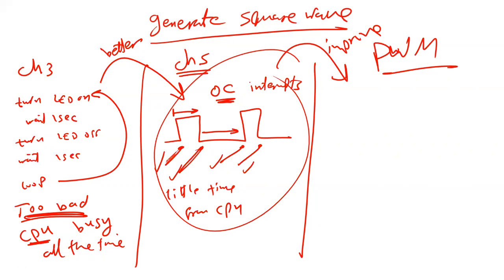Even if your interrupt subroutine is empty, just when you trigger the interrupt, number 1, automatically you have to push all the registers. Number 2, I have to pull all of them back. So there is already overhead, already computation. On top of that, I have to execute some code in the interrupt subroutine. You got what I'm saying?